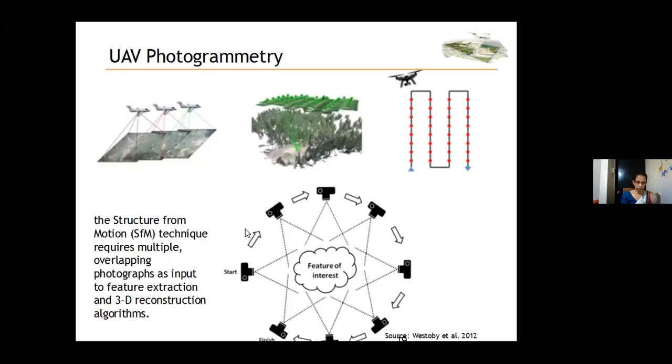It is an automated technique evolved from machine vision, and it requires a massive number of points, which also requires a lot of image overlap. We can reconstruct the camera model from the imagery alone without additional information like what we did in traditional photogrammetry. That is the important thing when working with modern photogrammetry.